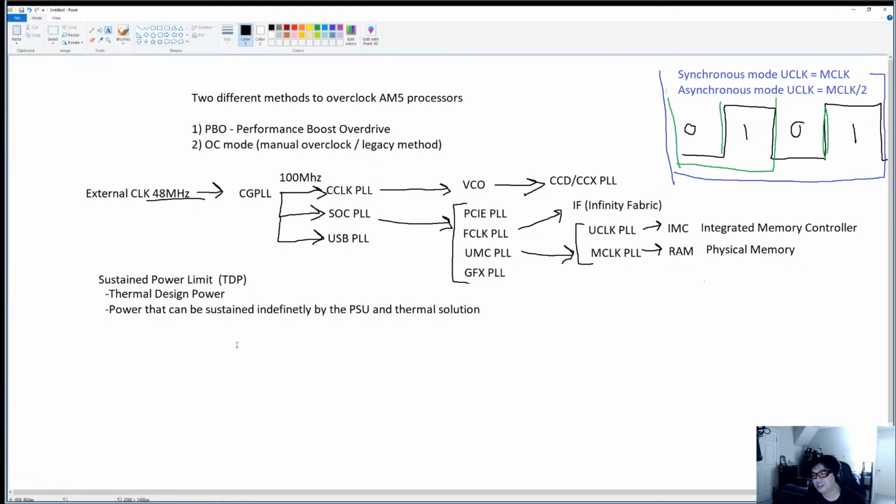So how good do you think the small form factor 750 watt gold PSU that comes with the... It should be fine. I wouldn't run a graphics card that's above 300 watts in there. So I would not run a 6900 XT or a 3080 or above in that case. I personally wouldn't do it, or at least not with that power supply. But a 12400F or whatever, plus whatever 250 watt or lower TDP GPU, will probably be fine.